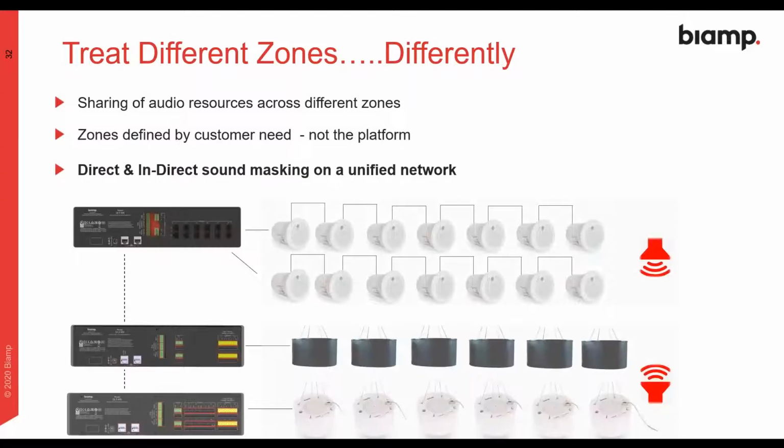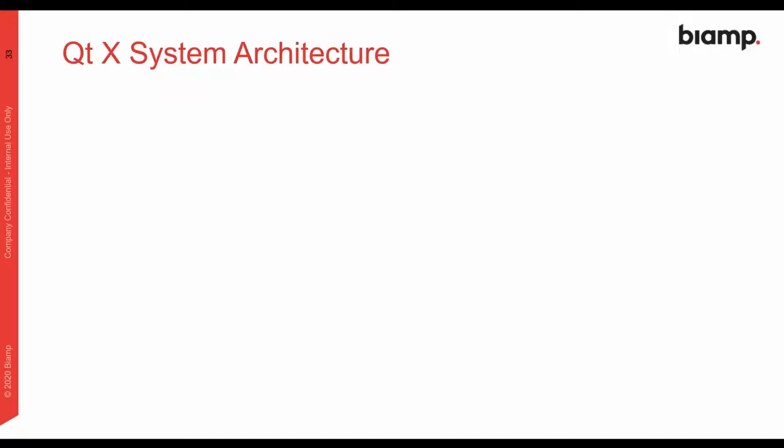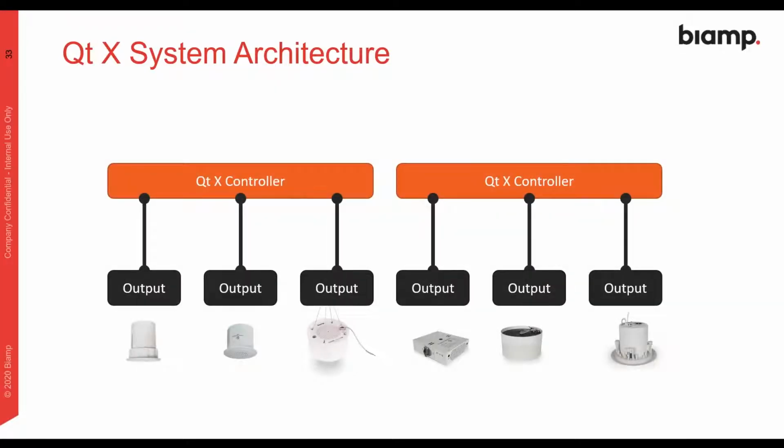So what happens is, as I'm building a system, if I want a group of emitters, passive or active, to get the same source and have the same overall level, where I've got a master control level, I've got that ability by grouping in zones. Now, I'll still have the ability downstream to change the output level or fine-tune as needed on a per-output basis, but my master volume for the zone is upstream from that. I'll show you that in an image here in a moment.